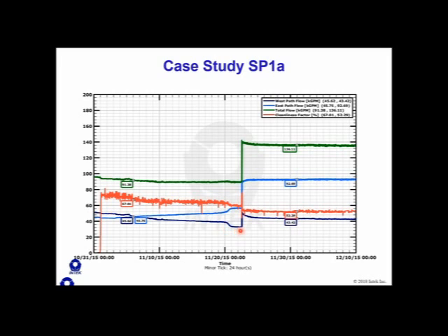And then in the total flow rate, you can see in the green line, it's just constantly decreasing. The one circulator comes on, it constantly decreases. And then when they turn on that second circulator, it's continuing to decrease. This is what happens when you get preferential debris fouling.